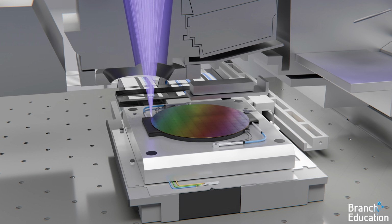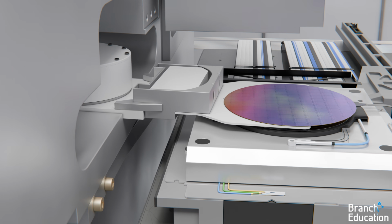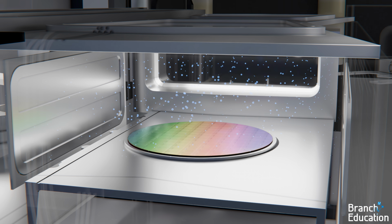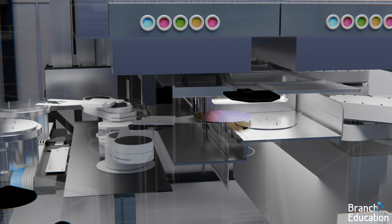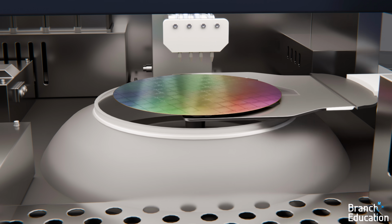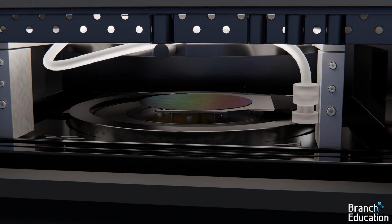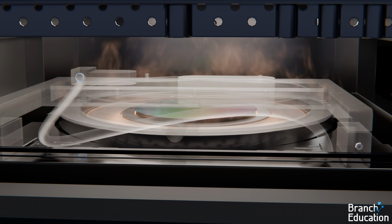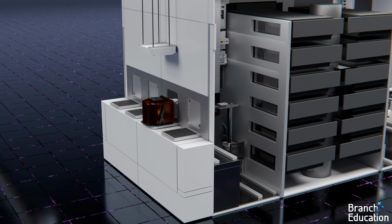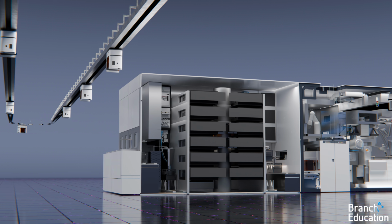Once all the microchip patterns are copied to the wafer, the stage moves back towards the robotic arms where the wafer is unloaded and placed into one of the vacuum load locks, pumped back to atmosphere, and then a separate robotic arm brings the wafer back to the track tool where the patterned and modified resist is washed away using a developing liquid. Finally, the wafer is heated again to further harden the remaining resist. The patterned wafer is then loaded back into the FOUP, which is picked up and brought to a different tool to undergo processing in other ways.